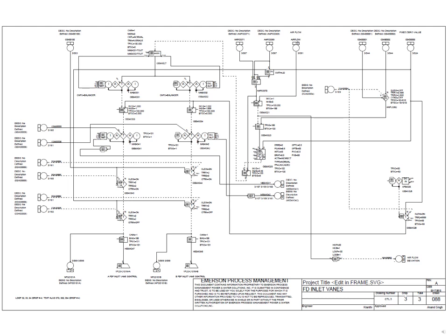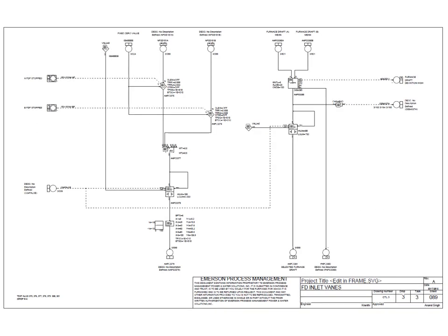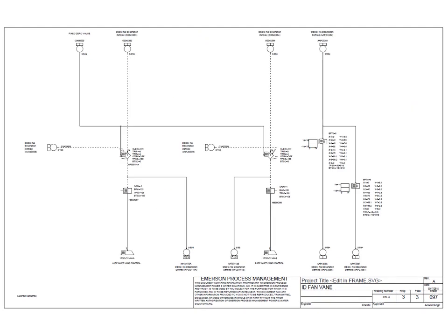And again, I would say that if you want to study or understand how control logic works or how control systems were implemented, use SAMA diagrams. But if you want to see, understand, or interpret what's happening in the plant or with the control system in real time, you should use signal diagrams, logic diagrams, or control sheets. And it is easier to analyze in real time if you know how control systems were implemented.